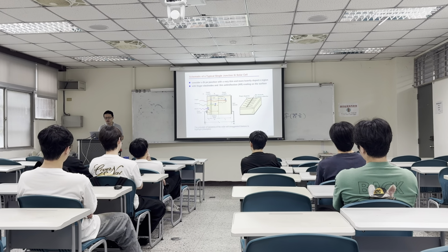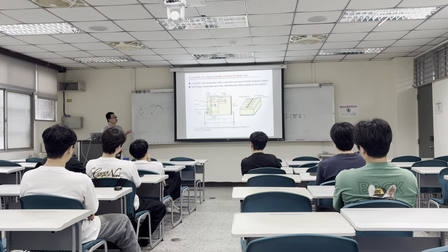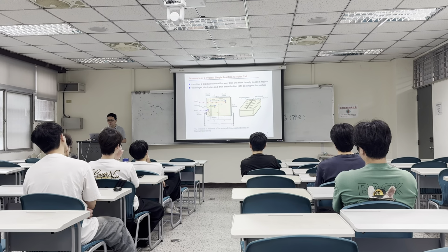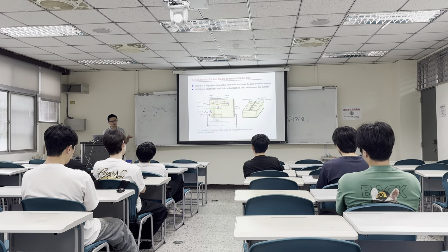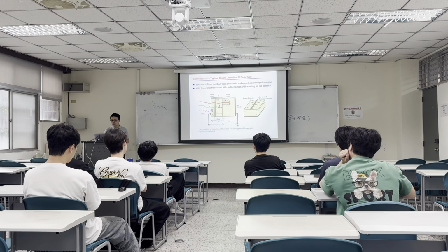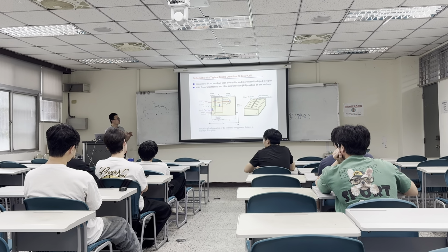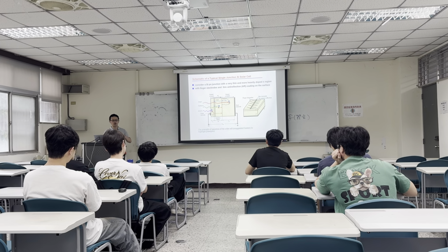So this kind of structure will have a heavy doped N region with a thickness of about 200 nanometers, and that's the diffusion region. And the bottom is about a 200 micrometer thick P region. Because you have to shine the light on the surface, at the top you cannot make a contact covering the whole surface.